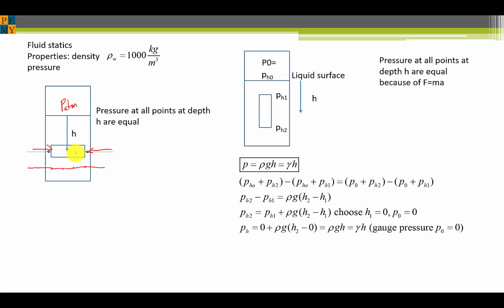be a constant. Now we're of course assuming that the thickness of this tube is very small so that the pressure doesn't change much as you increase in depth. Now if you flip the tube into a vertical orientation like this, the pressure at the bottom must be greater than the pressure at the top because it has to support the weight of this liquid in here, and we know that that doesn't move either under equilibrium conditions. Therefore, pressure again is not uniform with H, it's increasing.